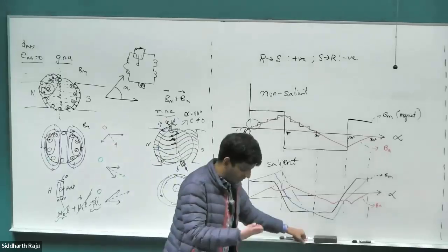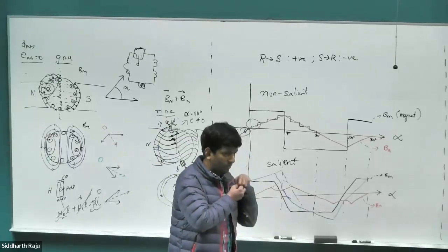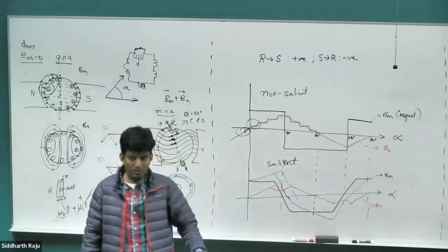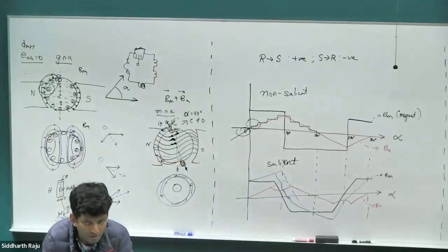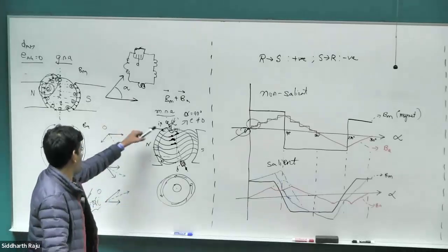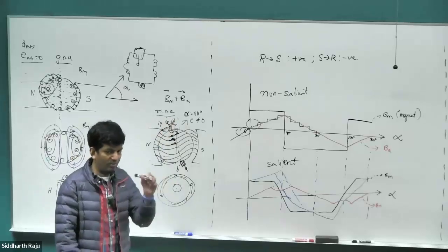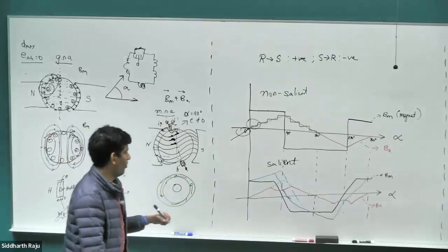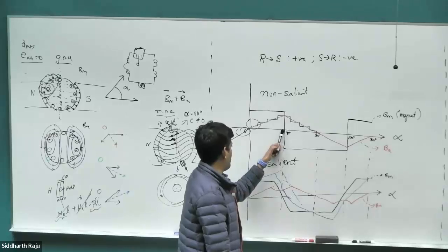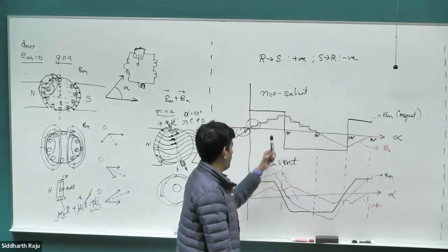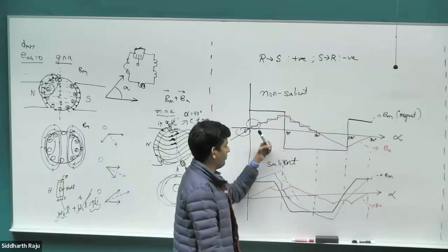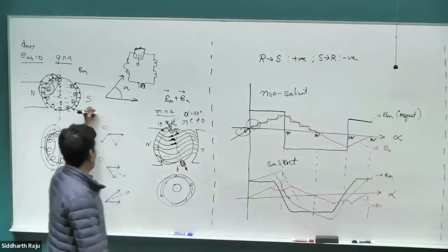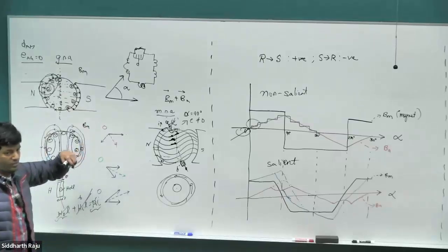Is 90-degree the only point at which the brushes short the two commutator segments? You've all drawn the diagram for homework problems 2 and 3. Was it only at 90-degree where the brushes short the commutator or no? So it starts to short at an angle even before 90-degree, right? The brush has some amount of thickness to it. So it is not only at 90-degree that we want the B field to be as close to zero as possible. Even before that, if we can somehow reduce the B field in the air gap, that means we can reduce the EMF significantly at that point.